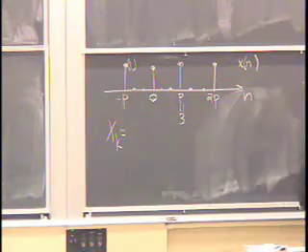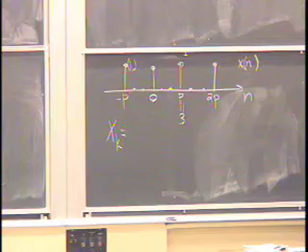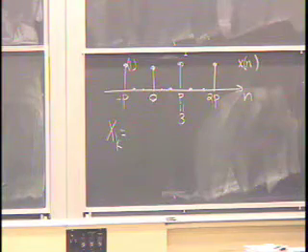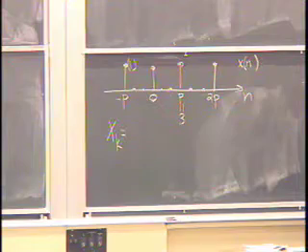In general, when you try to compute the xk's, the coefficients in the Fourier series expansion, whatever answer or expression you get typically has a dependence on k. In this signal, you actually won't get a dependence on k. All the coefficients will be the same. So if you don't get a k floating around in your equations, don't be surprised. This is a very special periodic signal.